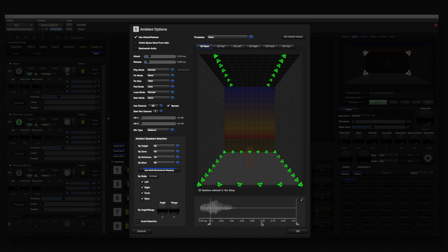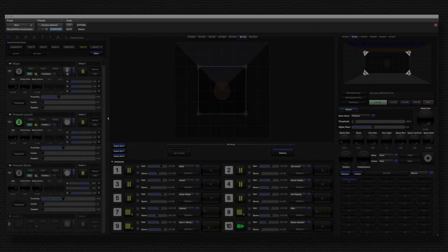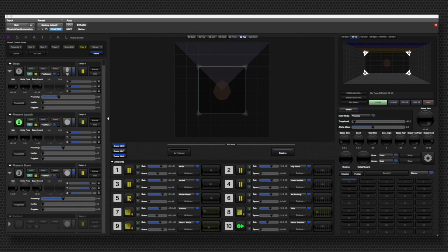Once the options of the environments are established, all that remains is to apply it to our mix. In the simplest mode, a play-pause control will suffice. In the instant pad press mode, the 3D positioning pad behaves like a trigger element, using the mouse down event as the shutter start, which at the same time we can move to set its position on the plane or the space.